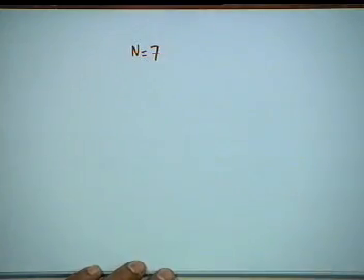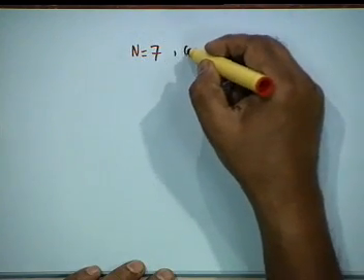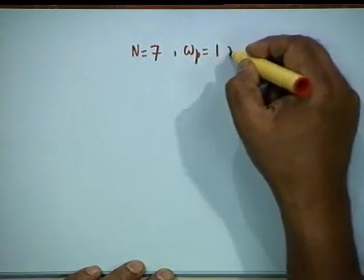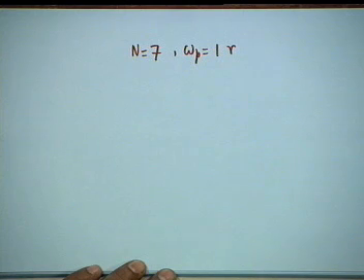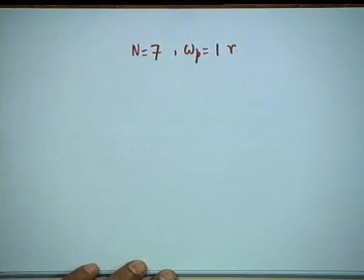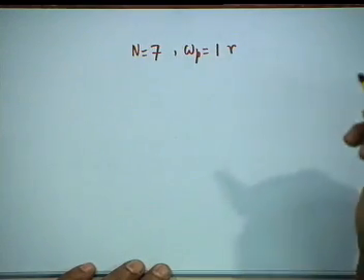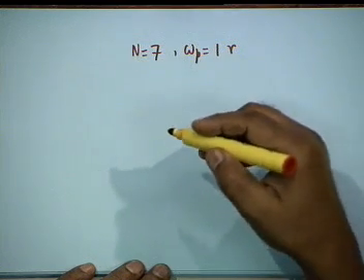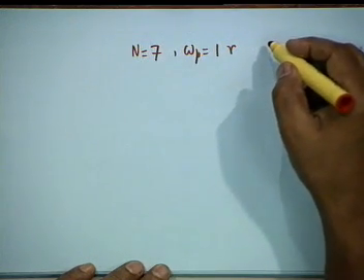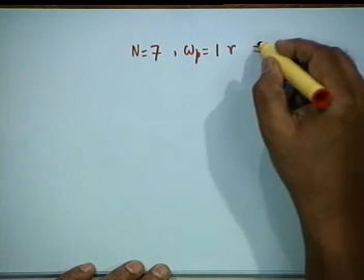Now, we had started an example. The example that we shall carry throughout is capital N equal to 7 and omega_p for the low pass filter is 1 radian, not radian per second. Okay. Many of the books make that mistake. In the figures, I have deleted per second from the figures, and N equal to 7 therefore leads to tau equal to 3.